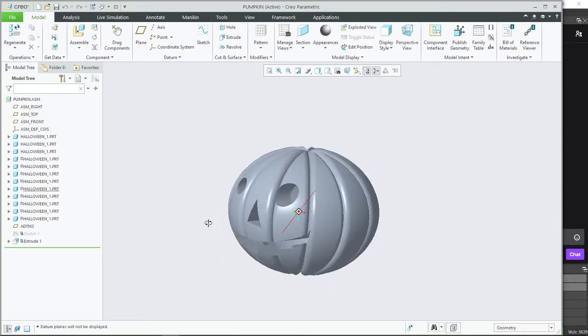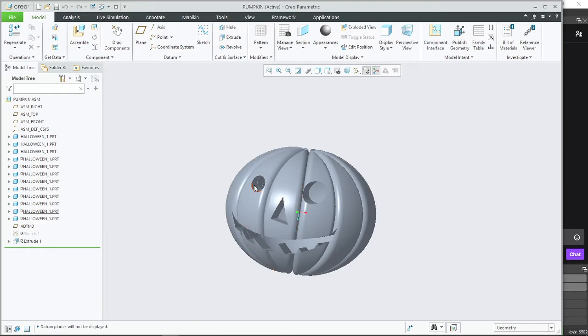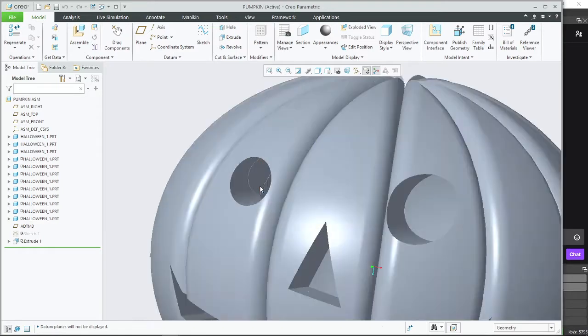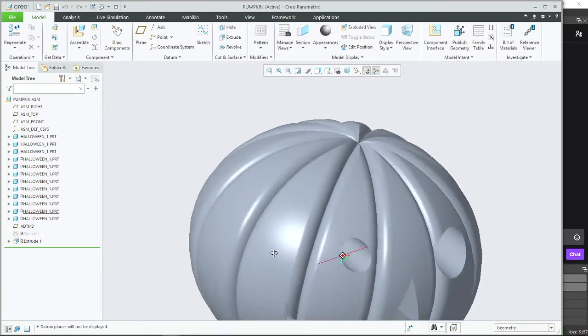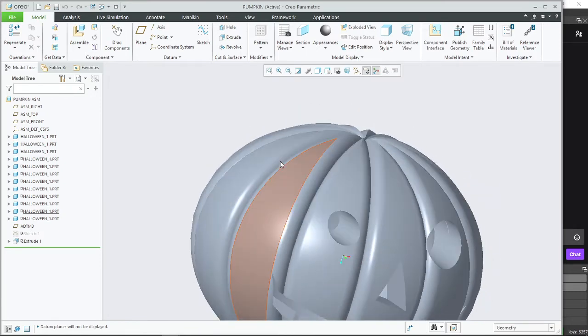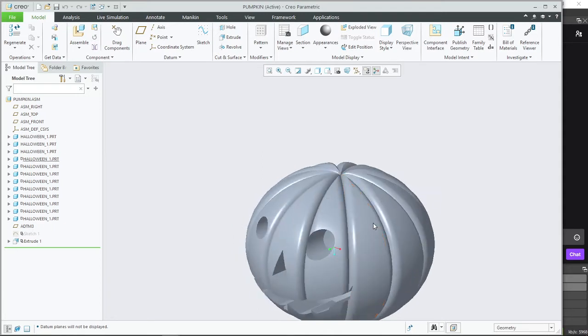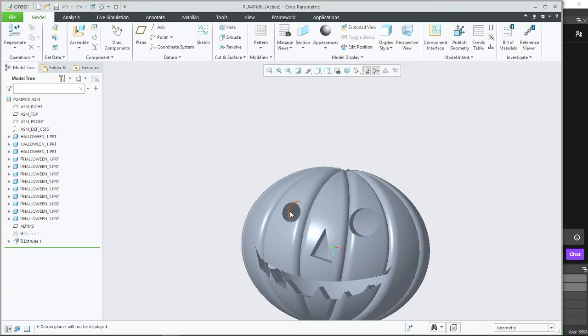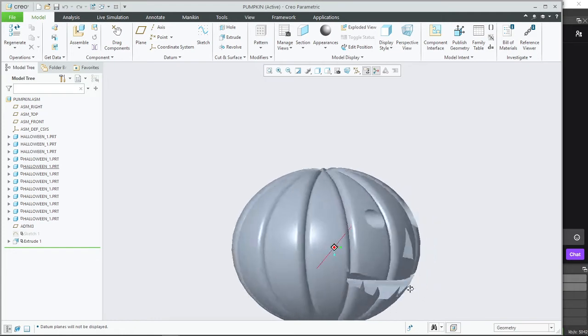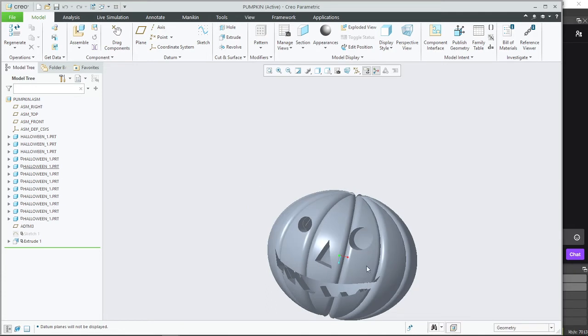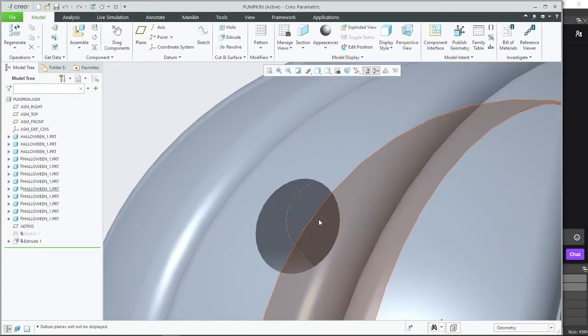You might see a little error at some point. You see this line that shows up here? Oh yeah. That error is there because I forgot to constrain one of the pieces. I didn't tell it that it needs to be perfectly joined to the next one. I said, please put it at 30 degrees. So it's indicating that it's not touching it. In actual production, it will, because we know how big the piece is. But it's doing so that you know that its constraint is not regarding the surface next to it.